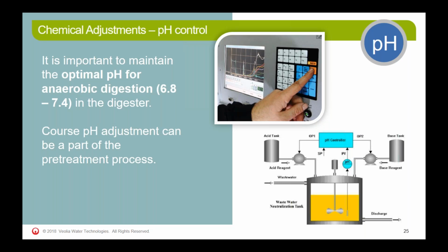We will see the pH swing in some facilities from pH of 2 to pH of 14. So in those cases, we might want to equalize the pH closer to neutral prior to treatment for multiple reasons. One of the reasons for treatment of solids, we would like to neutralize pH close to neutral because coagulants and polymers do tend to operate much better at close to neutral conditions.